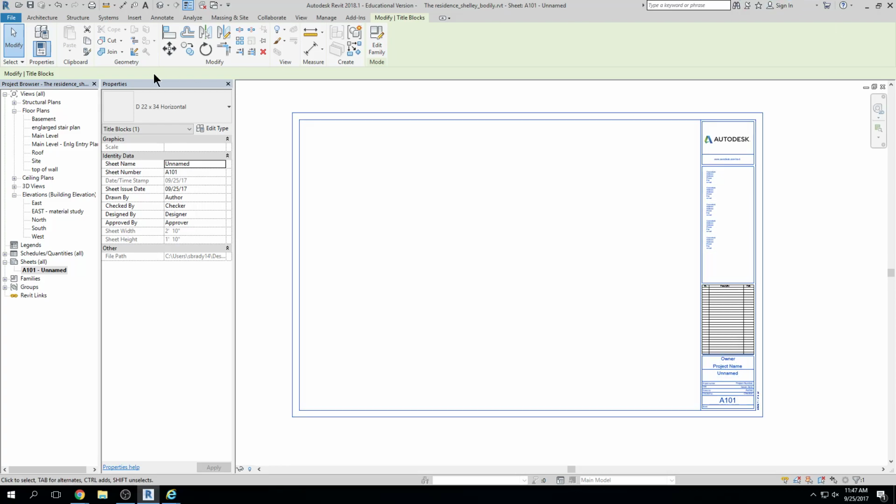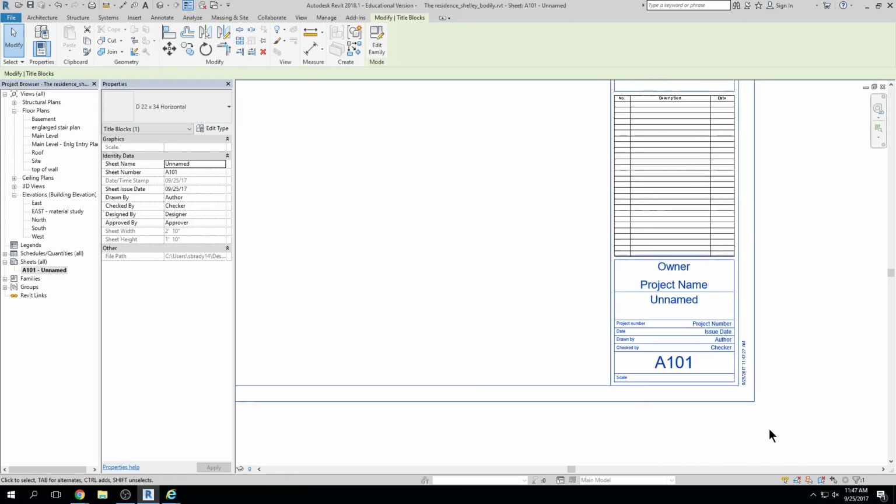Now, what's nice about this out-of-the-box Autodesk family is that it has some parameters set up in it. We're not going to talk too much about how they're generated yet. Just know that they are there. Parameters will allow you to change information in here, and it will coordinate through each of those title blocks. Here's kind of the magic of Revit. The owner, SLCC, enter. Project name, click.